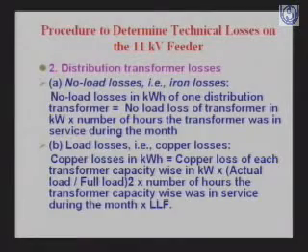No load losses, these losses will be written on the transformer nameplate. They are proportional to the supply voltage. If the voltage changes, this also gets changed. If the frequency changes, they also get changed. But for all practical purposes, we presume this as constant.